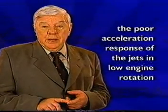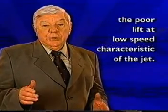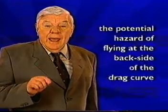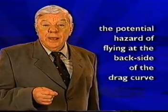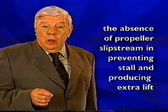Just to recall what we have said till now, a jet may be worse than a propeller aircraft in the following ways: the poor acceleration response of the jets in low engine rotation, the poor lift at low speed characteristic of the jet, the potential hazard of flying at the backside of the drag curve, the absence of propeller slipstream in preventing stall and producing extra lift. Put all these facts together, and you will see how potentially more difficult it can be for the pilot of a jet when making an approach and correcting inadvertent errors.